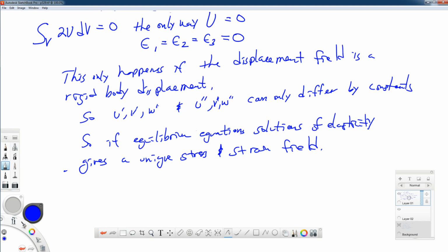This is not the case for things that behave like nonlinear plasticity. In nonlinear plasticity, we can have the same strain field developing from different stress fields. There's a path dependence, and we have plastic dissipation and different things going on where we're expending energy.